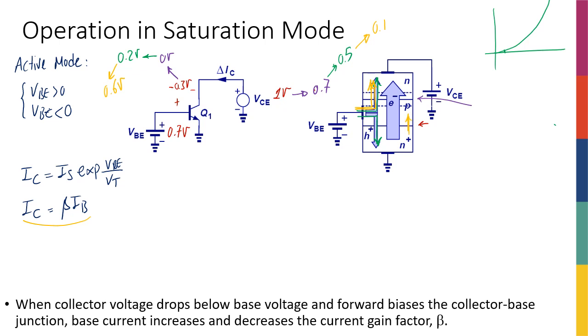Now I have two forward biased junctions, one between base and emitter, which causes all these electrons to travel from the emitter to the base. A lot of holes are also coming to the base, and they might recombine with these electrons. But because of the thinness of the base, this recombination is still not a lot, and a good portion of these electrons reach the collector.